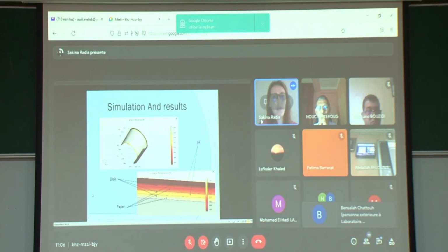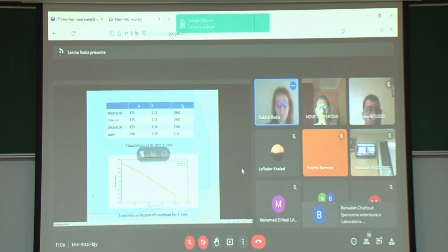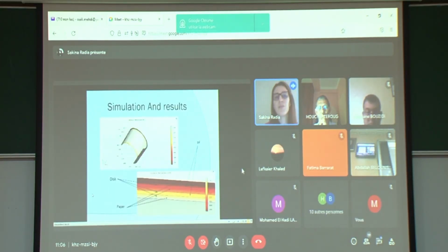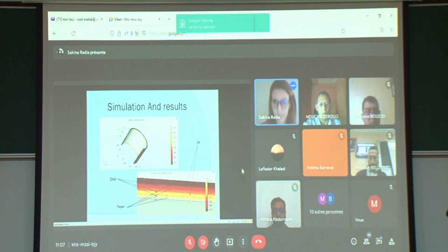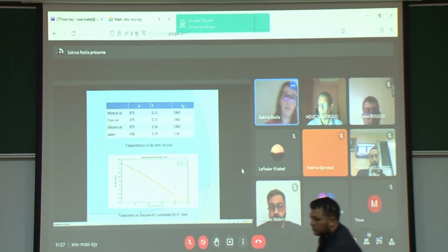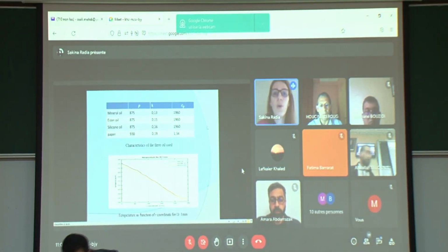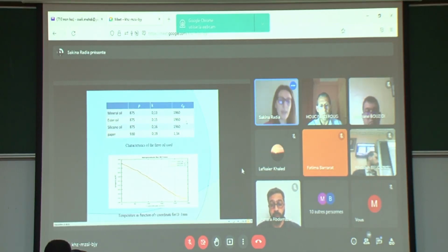In this work, the microtransformer is composed of two planar coils with octagonal form. The primary coil has 3 turns and the secondary 2 turns. The coils are stacked on magnetic layers of ferrite and dielectric layers of silicon dioxide. The following equivalent electrical circuit describes the electrical behavior of the microtransformer. We notice that at high frequencies, there is a creation of capacitive effects in the coils.